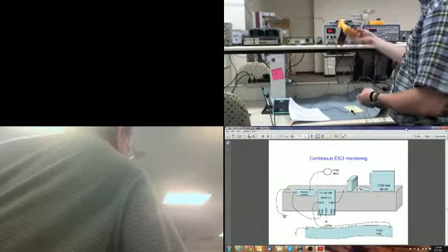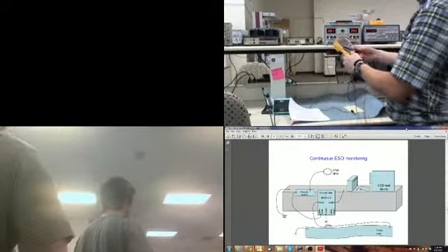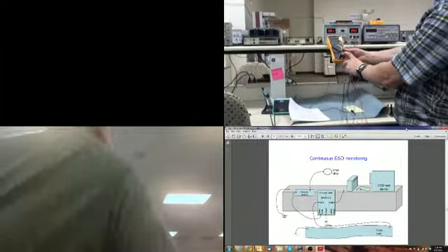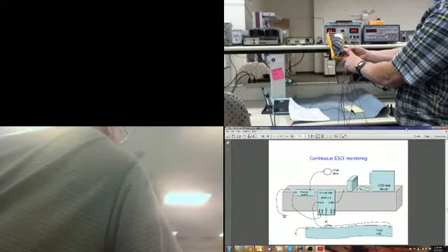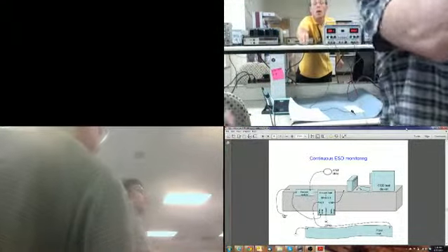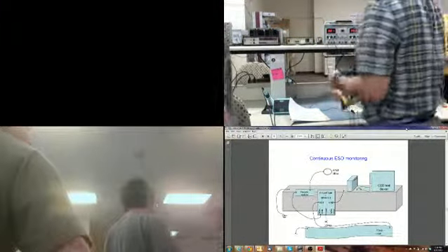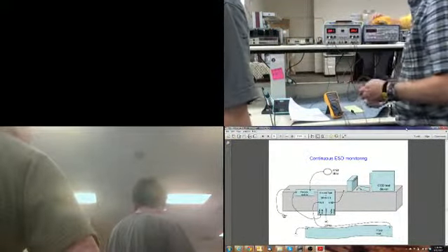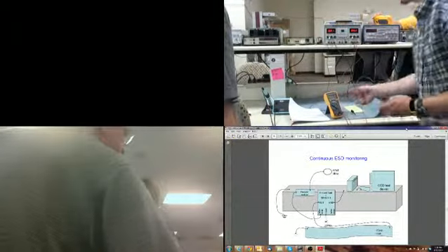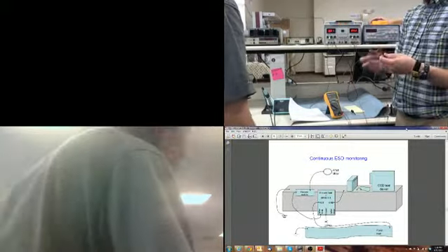The other feature of this DMM is resistance. And if Rocky could grab me just a resistor really quick, but first I'll do this capacitor. You see this reading here that shows a little capacitor symbol? The yellow capacitor symbol has two lines. That's for capacitor. All you have to do is put it on capacitor and then hit the yellow button. That'll switch it to that mode, and then you can measure your capacitor. It tells you the value of the capacitor.